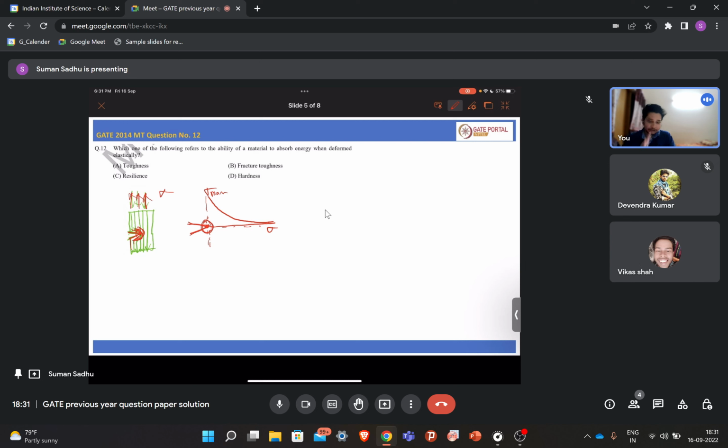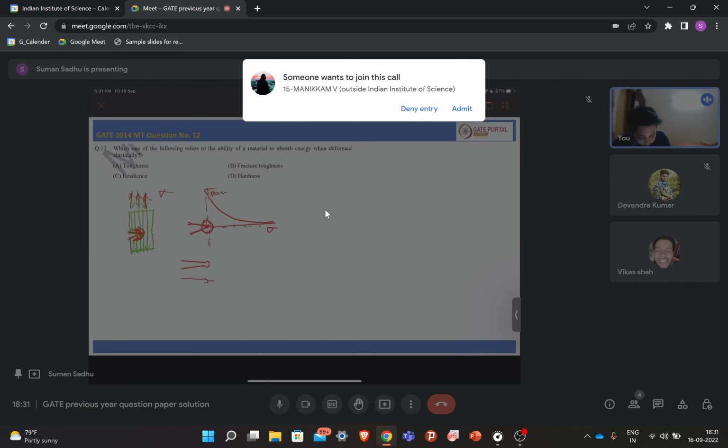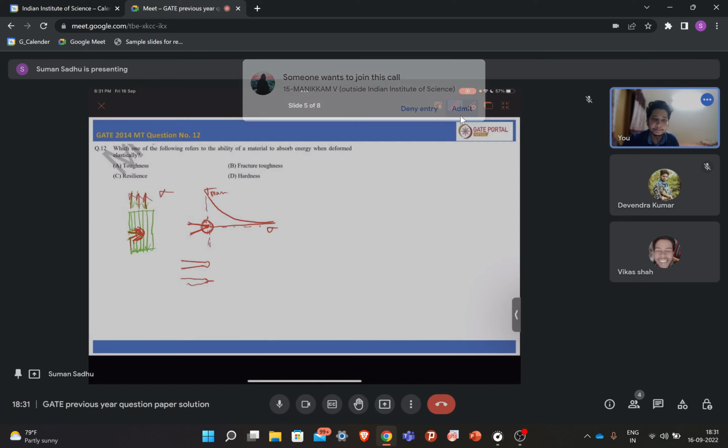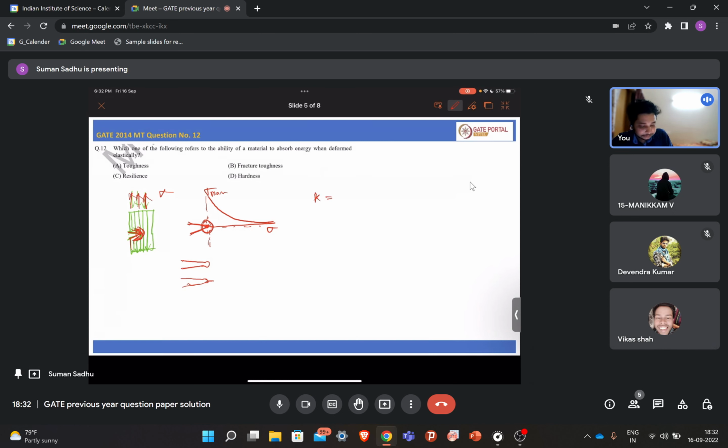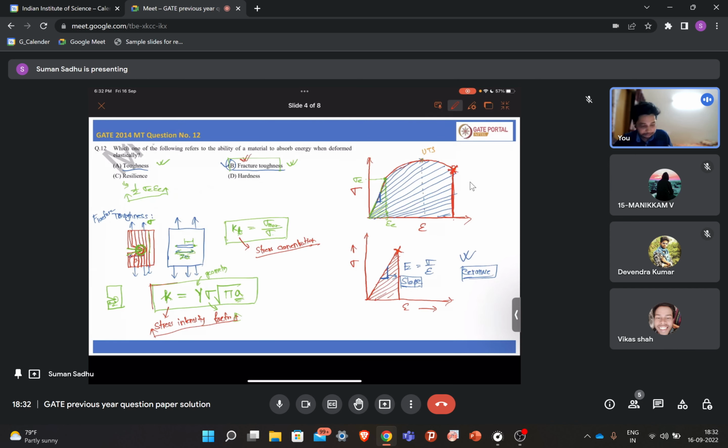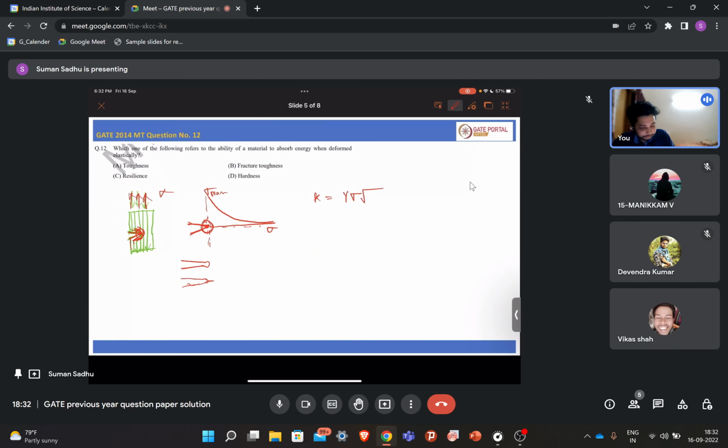If it is a plastic or ductile material, then first what will happen? Because of the deformation, the crack tip will get blunted. Okay, and when it crosses the limit, what will happen? Then this blunted tip will also crack. So again it will form one micro crack. This way, basically, the crack will propagate. Once the limit is reached, then what will happen? This stress intensity factor, whose formula I expressed earlier, right? So let's say this is pi a.